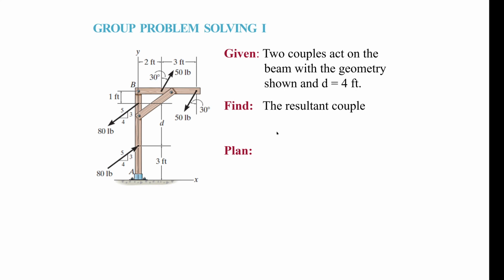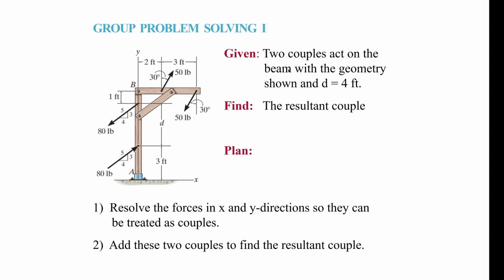All right. Group problem, okay? Okay, so this one, same thing, you're looking for the resultant couple, so you have a couple due to these forces here, and a couple due to these forces here, okay? So you have a couple different approaches. You could consider these to be vectors and handle them that way. Or since they're both in the same XY plane, it's probably easier just to think about them in terms of scalars, okay? So what we'll need to do is break these down into X and Y components.